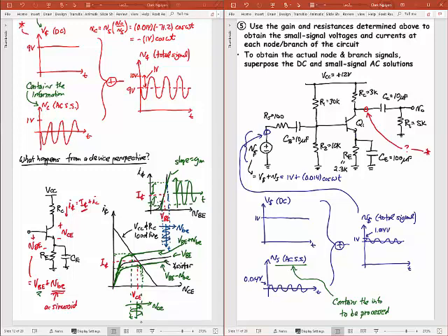And so if you had to give a rule of thumb for the input, how small should the input be in order for you to stay linear? If you had to give a rule of thumb for that. 1/10? Yeah, that's not a bad rule of thumb. But a better rule of thumb you can make by just writing out the IC equation. Right? So IC, let me do the total IC. Remember that was IS times E to the what? The VBE divided by VT.